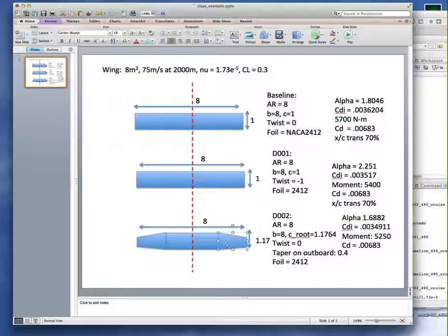So, and remember, the shear stress distribution over a foil from front to back is highest towards the front. So when you have a shorter chord, you actually, in a given area, you end up with higher shear stress. So making a longer, skinnier wing might be better for induced drag, but it might be worse for profile drag. So you may end up with some kind of trade-off, and eventually you're going to violate that bending moment coefficient. Probably you want to push the bending moment constraint pretty hard, because that's going to get you to higher aspect ratios.